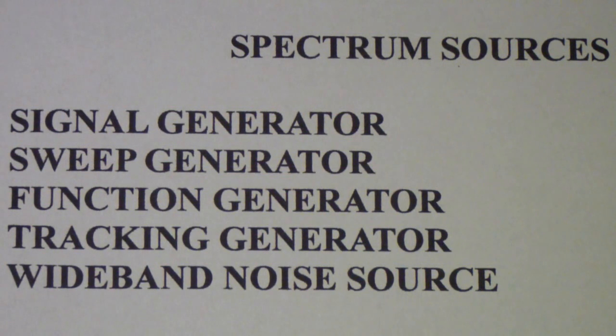But the problem is you're depending on the sweep generator happening to be at exactly the right frequency when the spectrum analyzer is also looking at that frequency. And you can improve the statistics by averaging over a long period of time using max hold and so on, but pretty inconvenient.